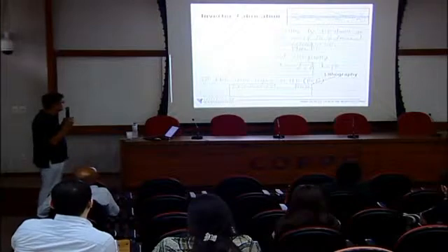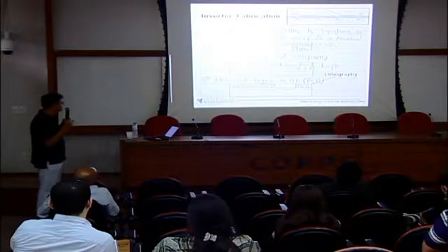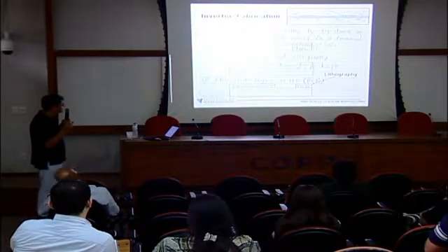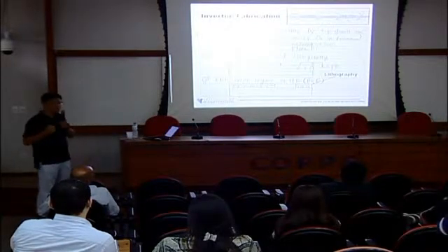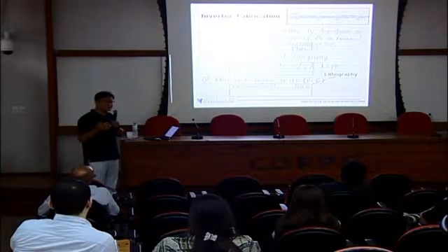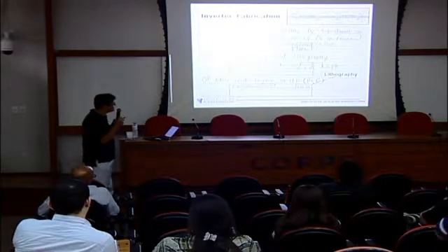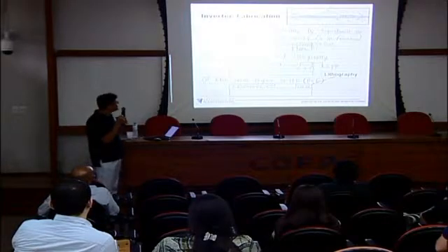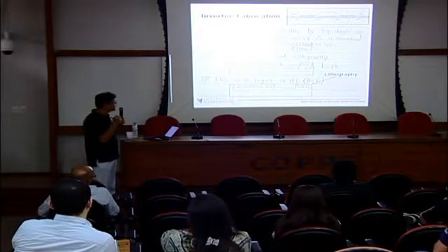Then photoresist will be spin coated on top. And as you see, the top part was open, right? Selectively open. That means we use UV lithography to open this window. Actually, this arrow should go there. So that's the first lithography step.